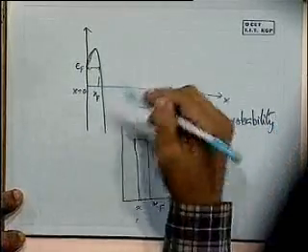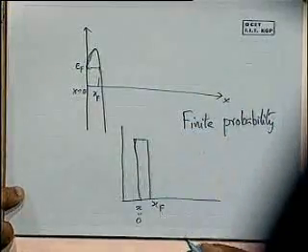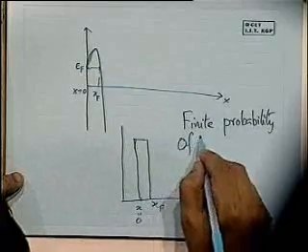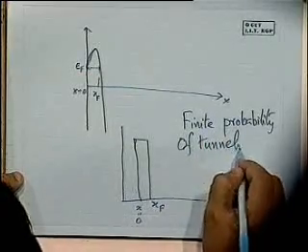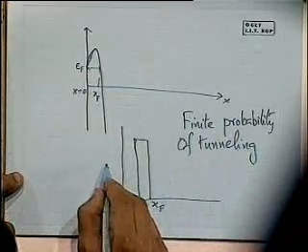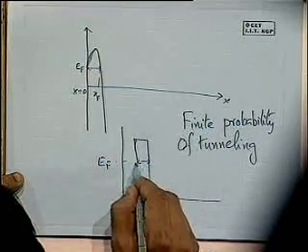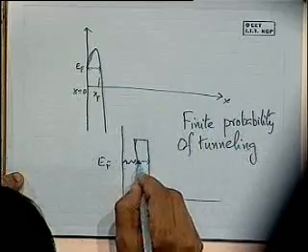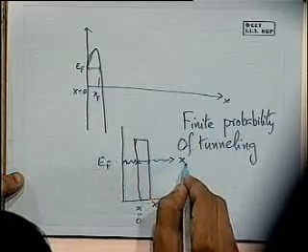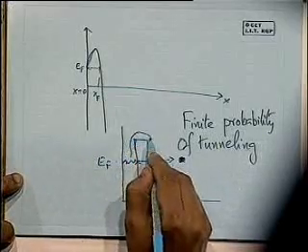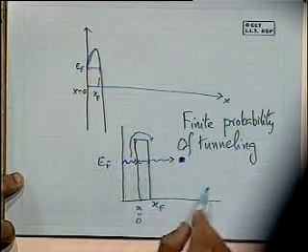Remember, always we are looking at a classical picture, making modifications according to our understanding of the quantum mechanical behavior. So in other words, an electron sitting at the energy level EF, where the barrier is xf, has a finite probability of tunneling through this barrier and coming out here. It doesn't have to go over the barrier to get to this side, it simply tunnels through.